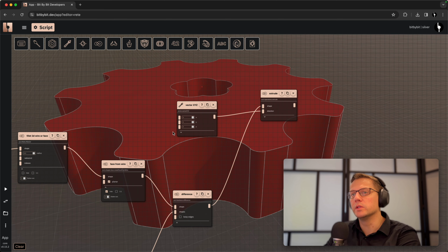So what happens is that now, if you preview this data, let's preview both the wire and the edges, you'll see that this contains multiple items, multiple edges in the list. And this just contains one wire, one shape in OpenCascade. And you see this hash is like an address in the OpenCascade kernel for the shape, and we use that to communicate with the web worker.